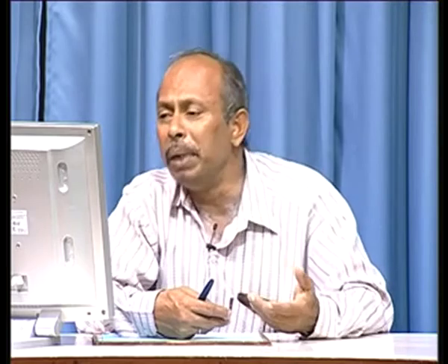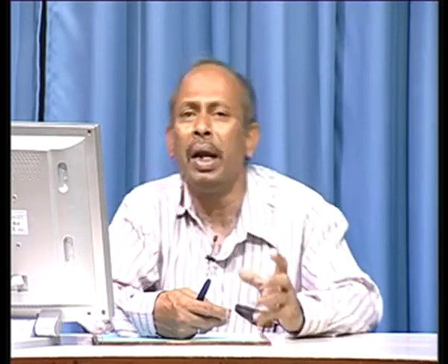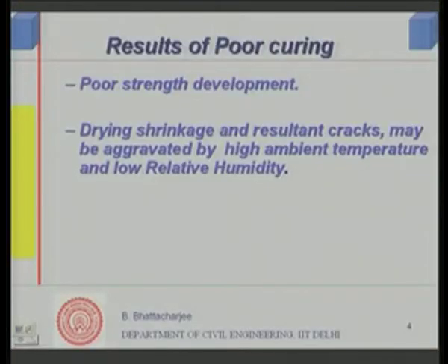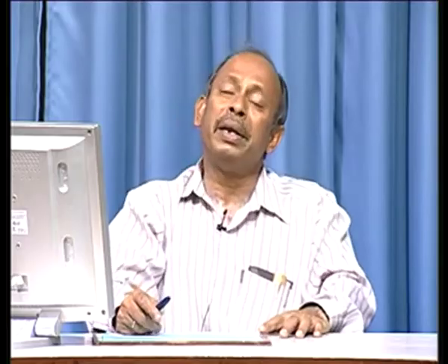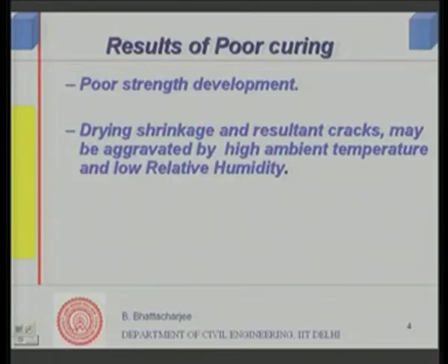Once things have become stable and the capillaries are segmented, the drying effect would be relatively less. So, in the beginning it is important that we avoid drying shrinkage, which could result in cracks. If we do not do curing, this can result in drying and shrinkage, and this might be aggravated by thermal effects. For example, in a hot arid climate in the northwestern part of India, we have high ambient temperature and very low relative humidity in summer.